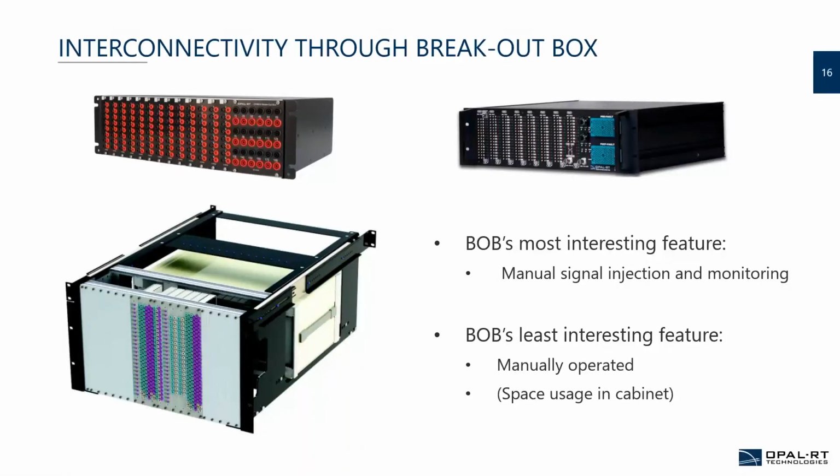For sure, once you find a solution, you will probably incorporate it as a fixed solution in the test bench. So basically, you will open the test bench and add this component. But the breakout box gives you open access to all those signals to advance quickly during the phases. So I strongly advise including some of those breakout modules in your systems during your design phase.